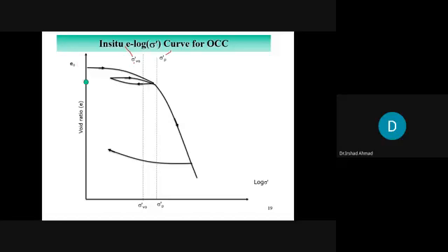You locate the point of e naught, which is the initial void ratio, and draw a horizontal line, and where it intersects the sigma naught prime, that is control point number 1 for you. Then you draw a mean slope between the swell curve and the recompression curve.